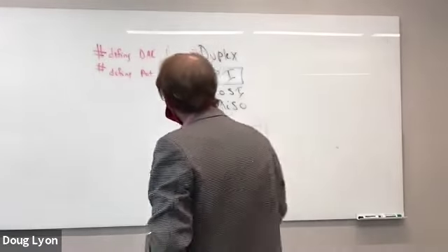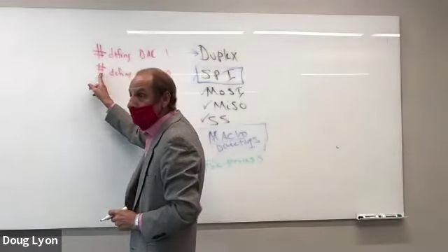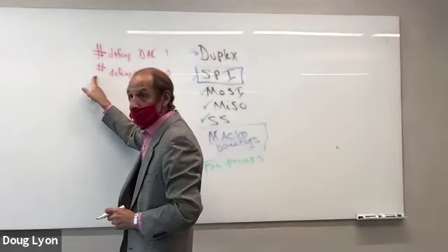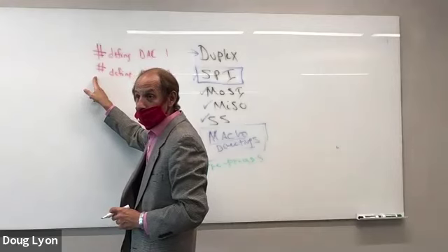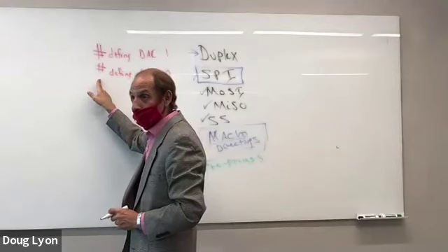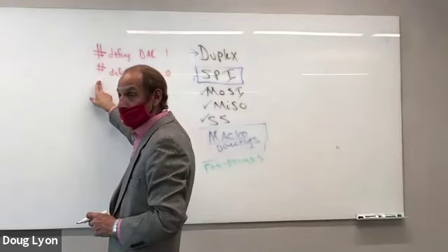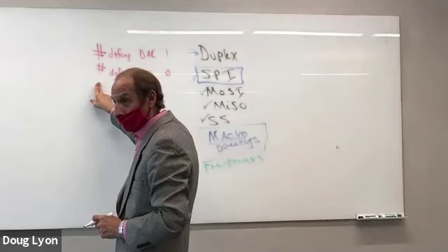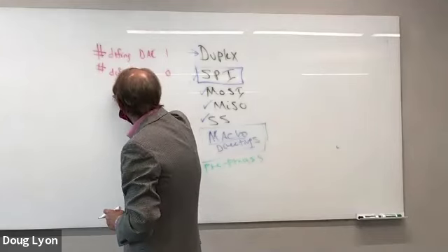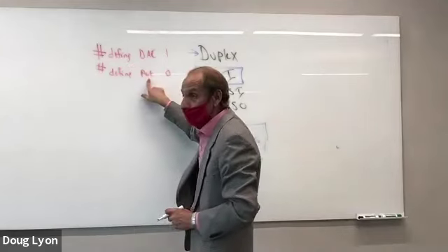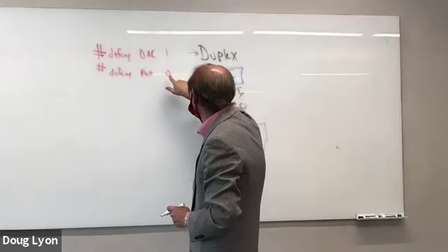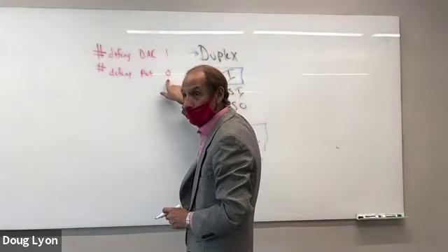First of all, look at these hash marks. These hash marks represent compiler preprocessor directives. These are macros. This is not going into the compiler directly. This goes into the preprocessor. Everywhere it sees the term pot, it's going to substitute the literal 0.